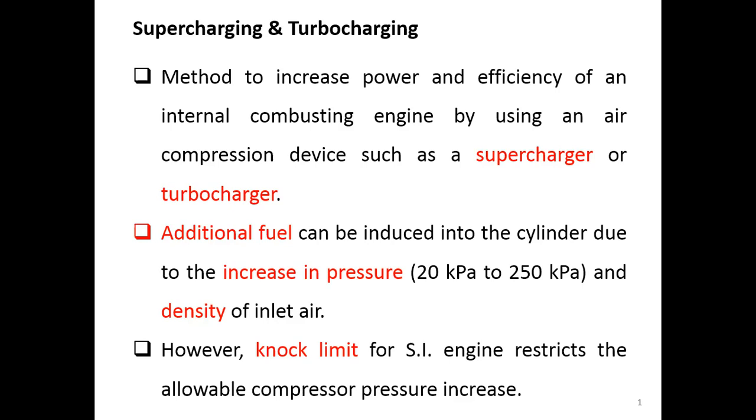Knock means pre-ignition before the spark happens. So when we introduce air through the supercharger or the turbocharger, we have to limit the pressure increase in the air because of the knock limit in the SI engine.